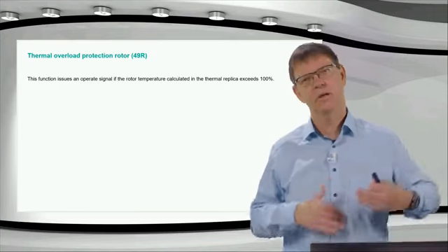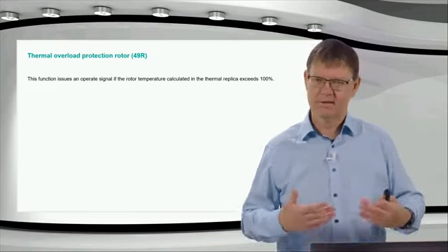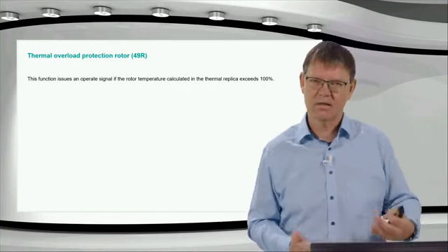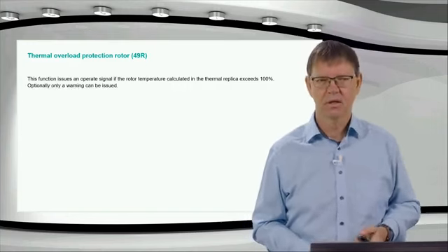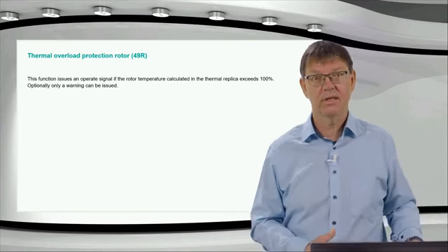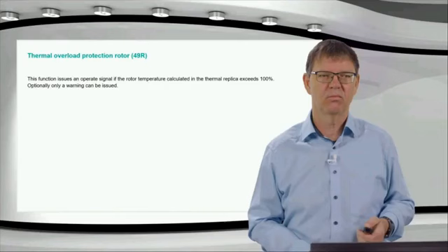If you say, okay, I want more safety here, I want a tripping if the calculated temperature is higher, then you can use this function. And basically it uses the same thermal model as the restart inhibit function, only that it gives a tripping command here.